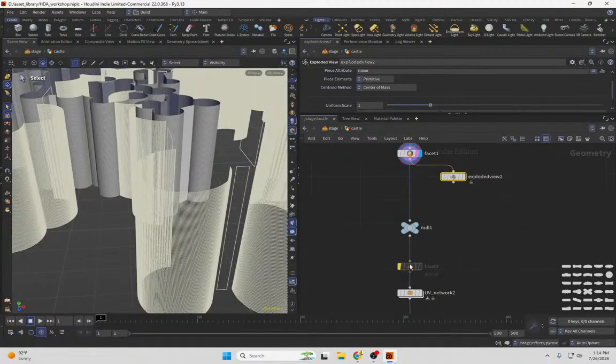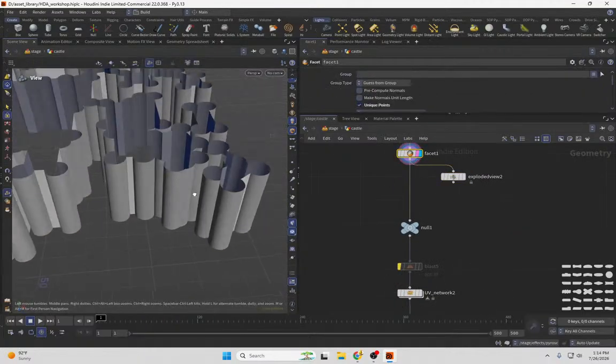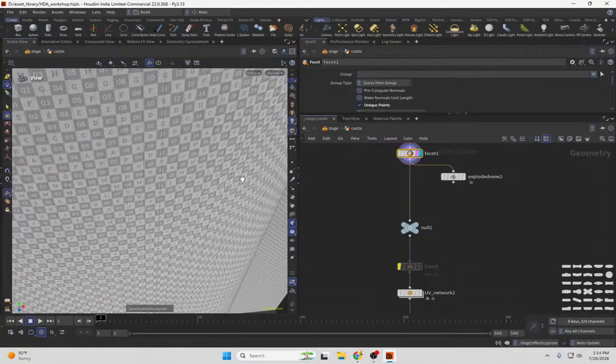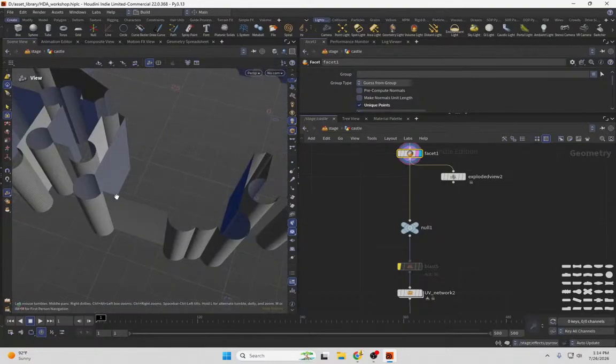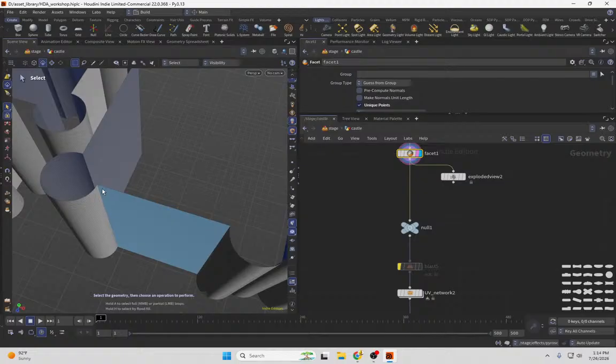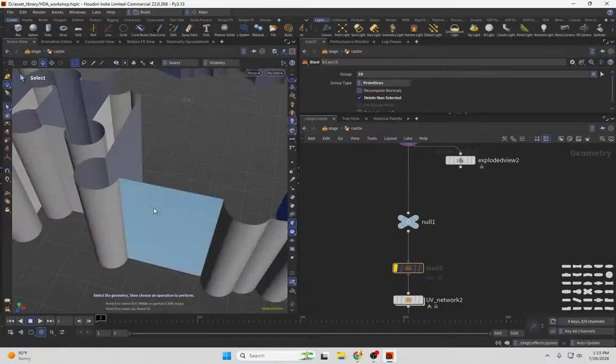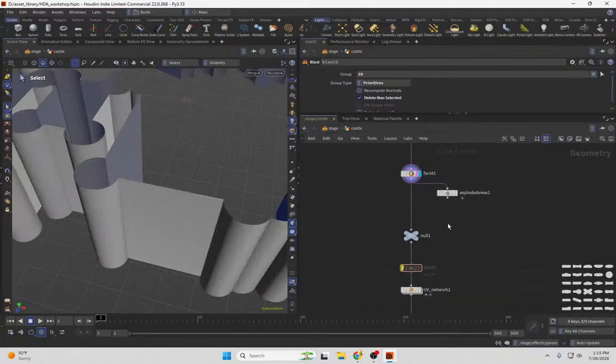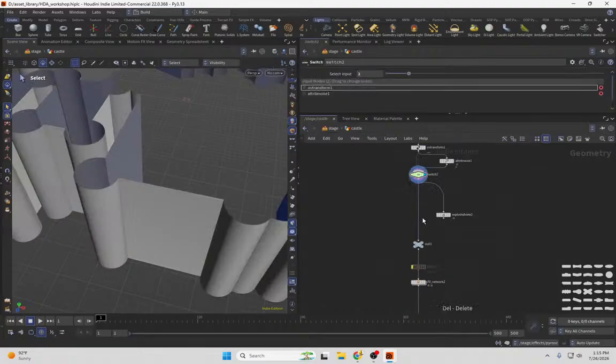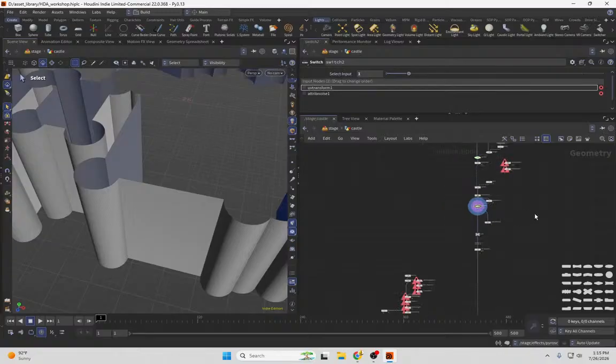Ideally, we only want this UV network applying to each individual wall, so basically reading the corners of the walls and then determining from that that each wall is, the walls can be curved like this. So facet's not a great tool to use for determining the walls, because curved walls will have multiple faces because it's based on polygons. So let's remove the facets, and let's think about this differently.